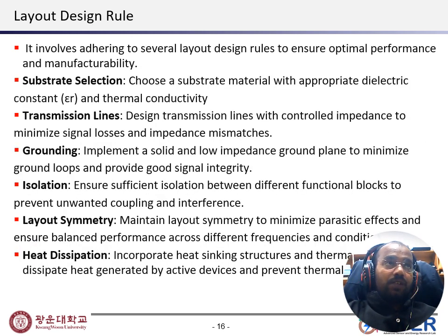Now we will talk about the layout design rules. It involves following layout design rules to ensure optimal performance and manufacturing. For that, we have to select a proper substrate having a higher dielectric constant and thermal conductivity, and also transmission lines designed to control the impedance to minimize signal loss and impedance mismatch.